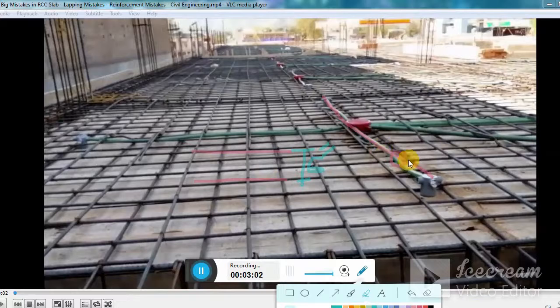While, if you are providing a 1-inch pipe over here, it gives you a thickness of 5 inches at this section. Okay, at this section. Now it decreases the thickness of the slab, you can say, up to 1 inch. Okay. Now it creates a weaker section, and there will be a chance of the slab cracking at this line. Clear? Similarly at this line. Sometimes they use so many pipes. So you should never allow such kind of conduit system.